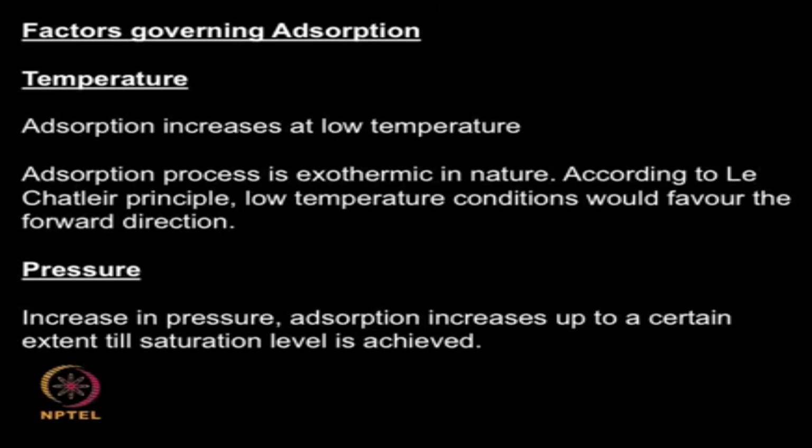Generally we keep the temperature low, you are going to have a forward reaction, but at high temperature, according to Le Chatelier's principle, it will not favor the forward reaction. So you will end up having a desorption. So at low temperature you can have good adsorption, whereas at high temperature you will end up having a desorption.